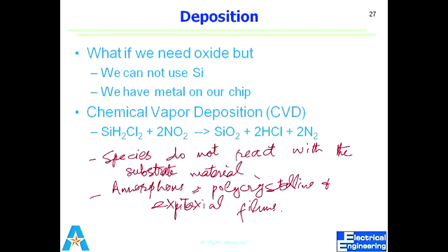But maybe in the final exam, Dr. Iqbal will assume that if he's talking about the deposition method, you will exclude the thermally grown method. So what method gives the best oxide? In the deposition method or generally? Generally, we always consider the thermally grown oxide, the native oxide at room temperature, to be the best oxide layer. In the deposition methods, there is plasma enhanced deposition, PECVD, and the best one is done at low pressure. Plasma enhanced is not good quality. So LPCVD is the best one. LPCVD is better if we talk about PECVD and LPCVD.